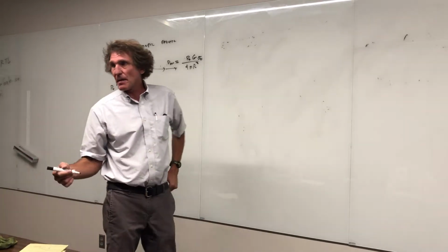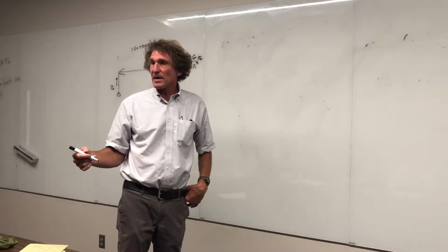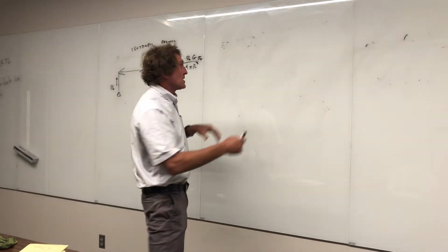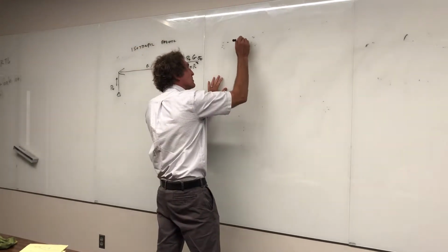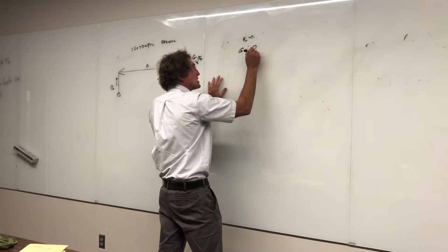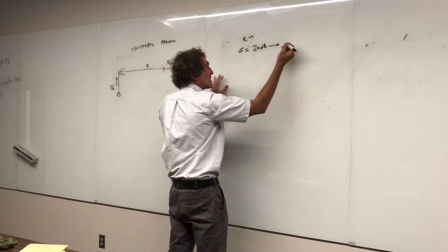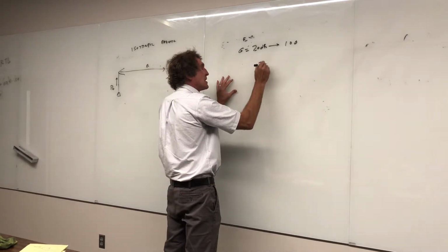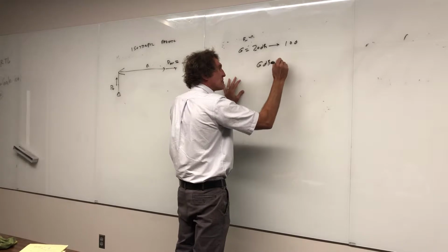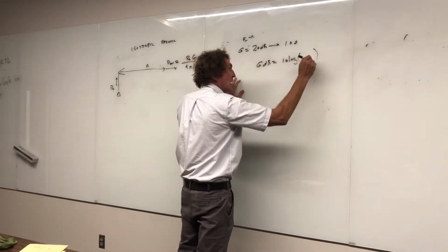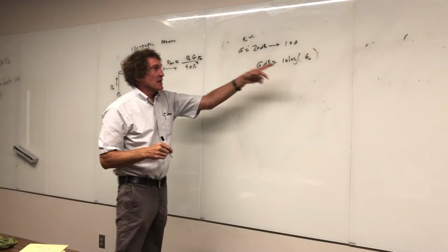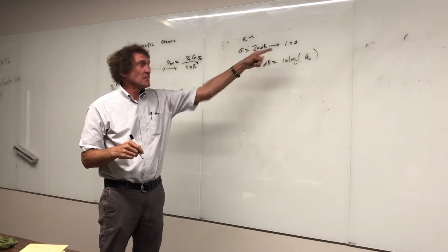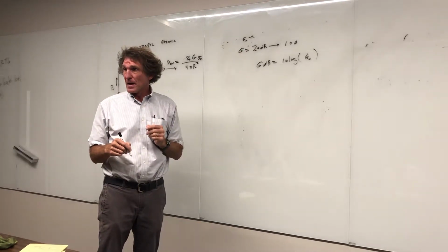Here's a real example. Say I buy an antenna that has 20 dB worth of gain in the main lobe. That means it has a factor of 100 of actual gain. So I've got 20 dB, and this is an example. So gain is 20 dB, or in a linear sense, it's got a value of 100. And everybody knows when we talk about gain in dB, well, maybe you don't, that's going to be equal to 10 times the log of the actual linear gain. So if you got 100 there, 100 is 10 squared, right? The log of that is 2. 2 times 10 is 20. 20 dB is 100 linear gain. Follow me, everyone?